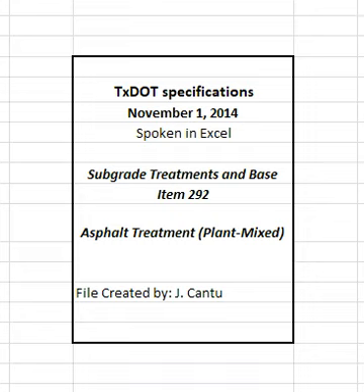The fine RAP stockpile will contain only material passing the 3/8 inch screen or 1/2 inch screen unless otherwise approved. The engineer may allow the contractor to use an alternate to the 3/8 inch screen or 1/2 inch screen to fractionate the RAP. The maximum percentages of fractionated RAP may be comprised of coarse or fine fractionated RAP or the combination of both coarse and fine fractionated RAP.